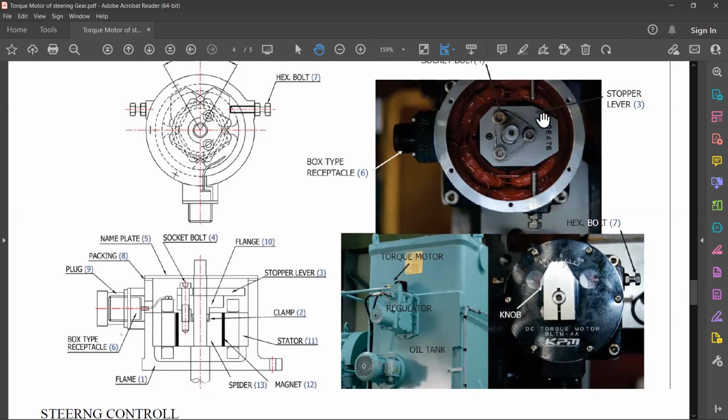Okay, it operates like that, and this will move in whatever directions you can move it. It will come directly over there. So suppose this entire thing stops working also. Okay, so that means your torque motor stops working. At that time, you can disconnect the electronic controls and you can actually control this by hand. So this is also serving as the hand control for the emergency operation.